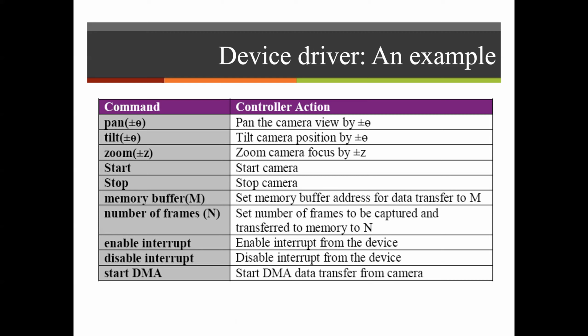Specifically, the device driver is going to control the memory mapped commands that are needed for the CPU to specify appropriate functions for the camera, which could be zoom, tilt, adjusting the X and Y coordinates and whatnot. So these are all commands that the driver has control over and can be implemented using DMA for the data transfer.